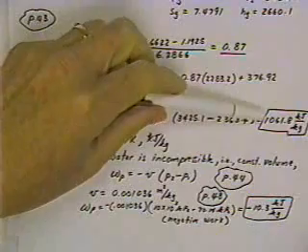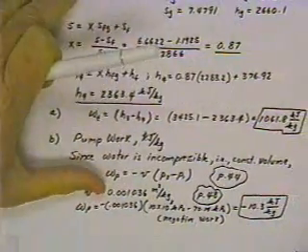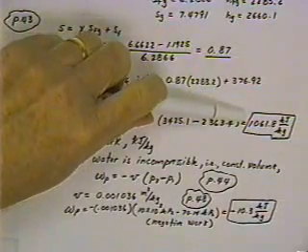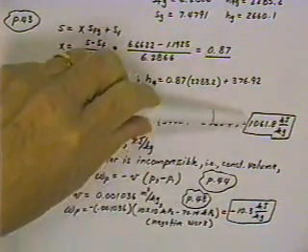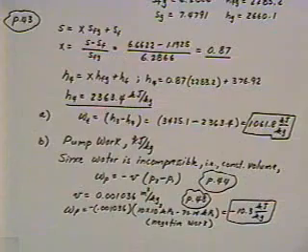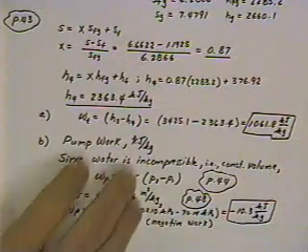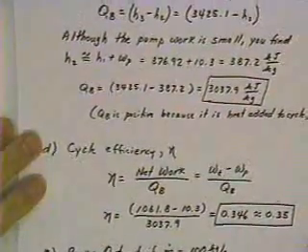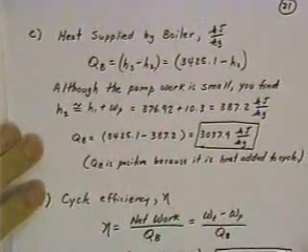But if you look back at the turbine work is 1061.8. So the pump work actually represents only about a 1% penalty when we're pumping the liquid up to the higher pressure condition. Okay, so we've now calculated the work of the turbine in kilojoules per kilogram. We've calculated the pump work, which is minus V times delta P. And so now we'll go to determining what the heat supplied is for the boiler.